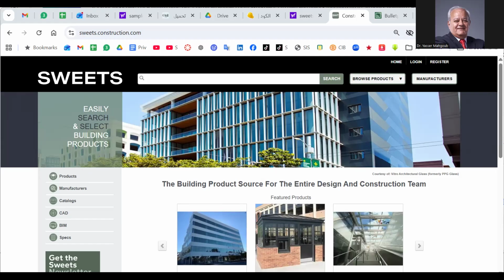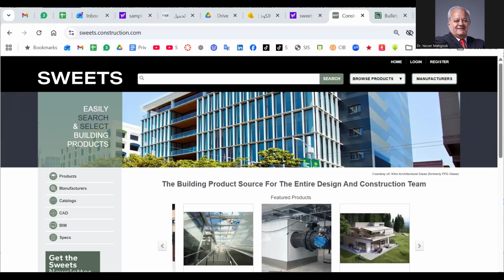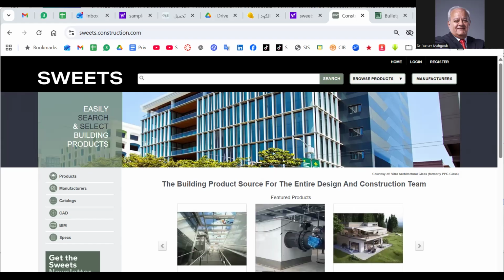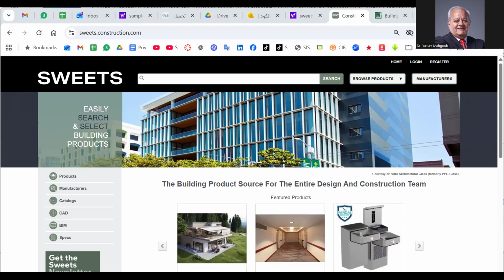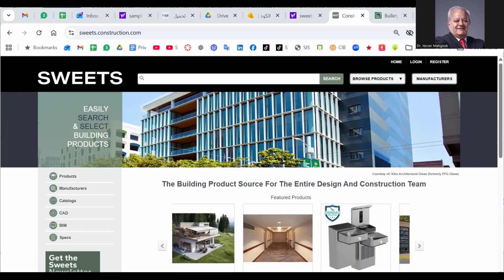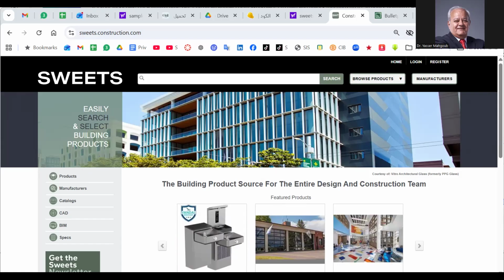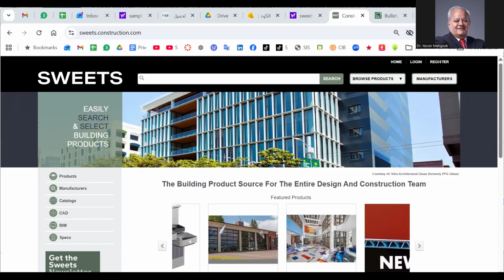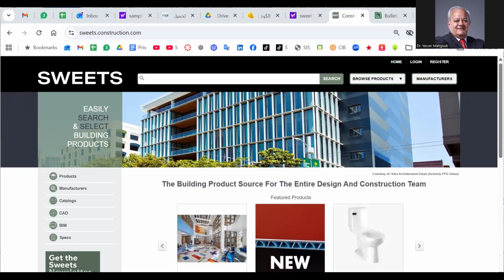So these blown up parts are extremely useful for, of course, this is the doors and windows tables. So each window or each opening type must be shown separately. Plan, section and elevation and dimensions and number of units and specification.